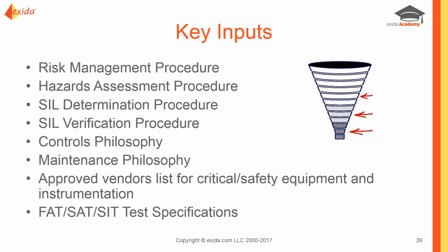There are key input documents that are going to be needed at these various stages. This is just a partial list of some of those. Most facilities may already have the hazards assessment, the risk procedure, maybe even the SIL determination procedure in place. We want the SIL verification procedure because that outlines what methods we're going to use, what assumptions we're going to use, and our basis for the calculations.